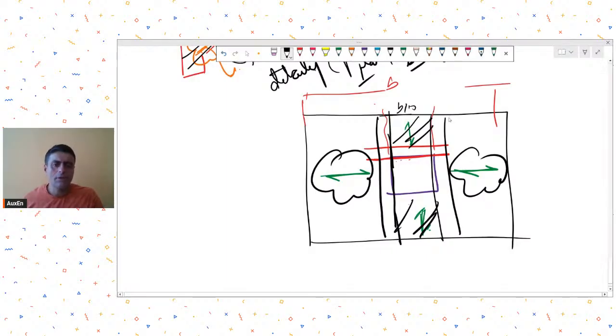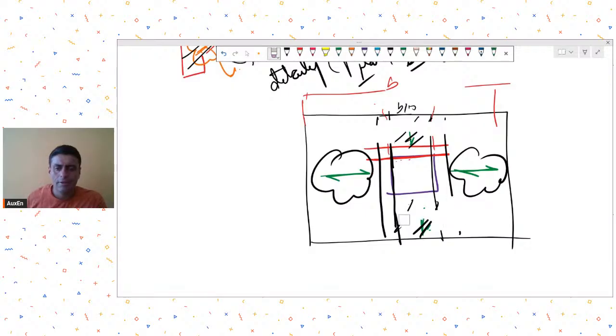If you don't have large openings, or if you don't have openings which are going to be loaded, then you could have these types of concealed beams provided, where these concealed beams generally have reinforcements at top and bottom both.